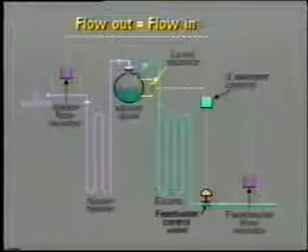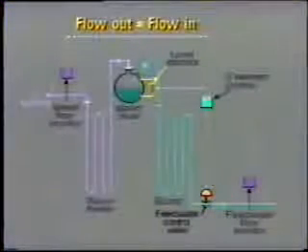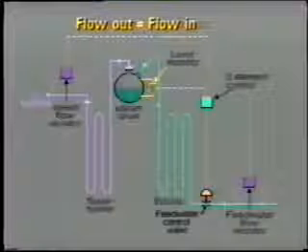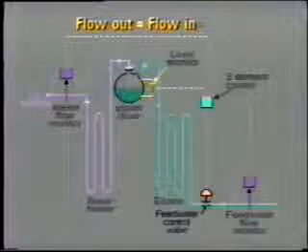The control system adjusts the feed water control valve so as to keep the two flows in balance, but at the same time allowing the control to be trimmed by the actual drum level. This is important because the two may need to operate in opposition at times.